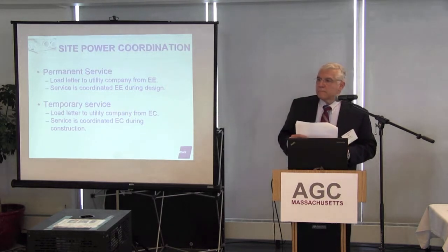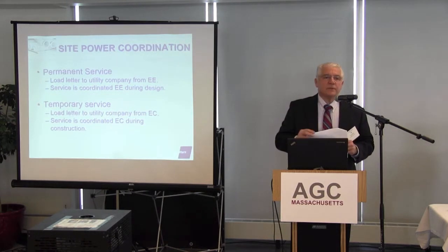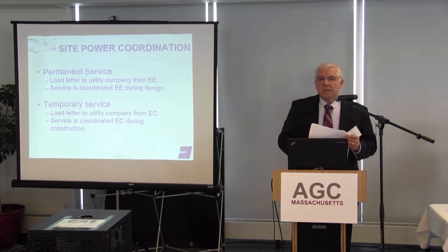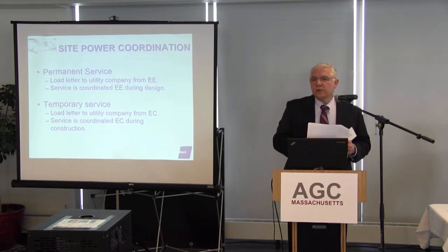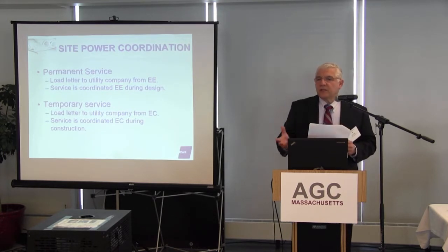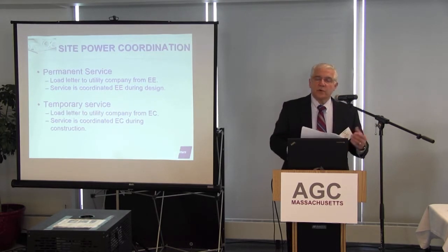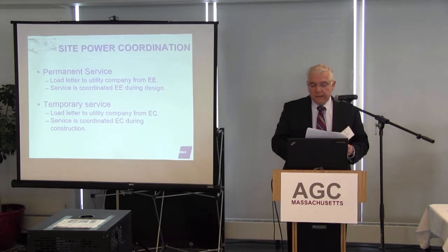How about the metering? Well, once we get inside, and I think we'll talk to that, but the metering, if it's a switchboard, there's a metering compartment inside the switchboard. Depending on the voltage of the service, there's a current transformer section of the switchboard, and Will's going to talk about that in the next section here.